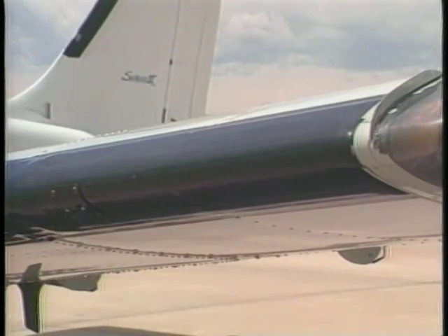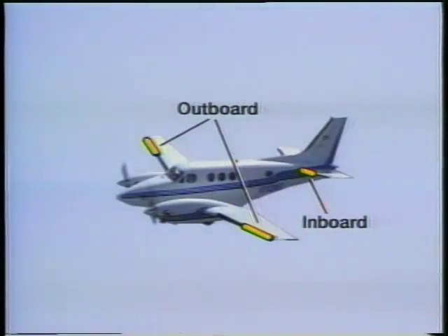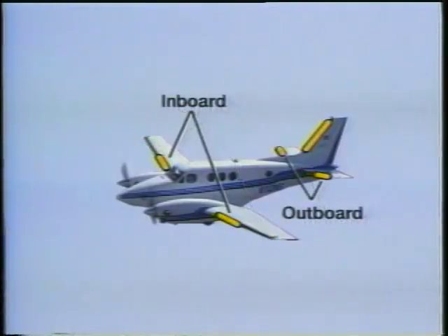The timer controls the inflation-deflation cycle. The regulator ensures the boots don't overinflate. It also may alternate the inflation and deflation of various sections of each boot to minimize the disruption of the airflow caused by the inflation of the boots.